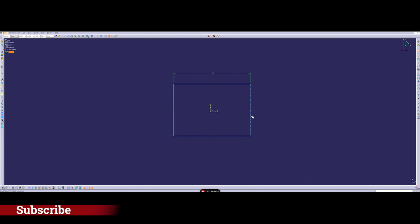So if I want to constrain my model to be always in the middle, if I want my origin, my three axis, to be always at the center of my part, which is actually the correct way to design, what we can do is click first the two edges and after the symmetrical axis. So, for example, this one.